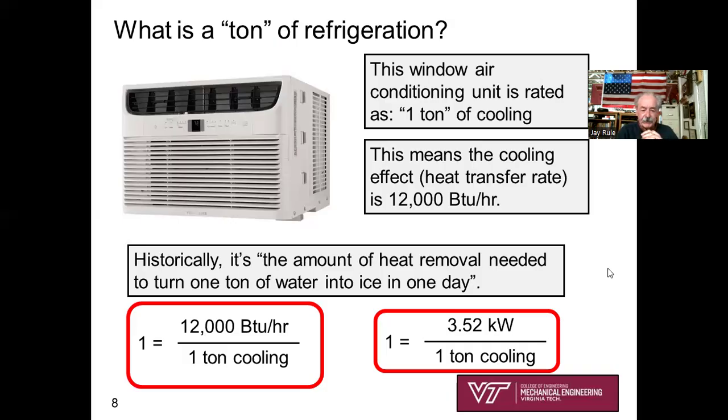Okay, so anyway, what's your conversion factor? Enough of the history. If you've looked at my videos, you see that I love multiplying things by unity, and that's what enables me to keep my units straight. So unity equals 12,000 BTUs per hour divided by 1 ton. That's an expression of unity. It could also be called a conversion factor: 12,000 BTUs per hour in 1 ton.